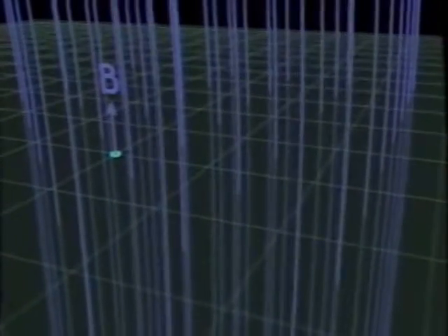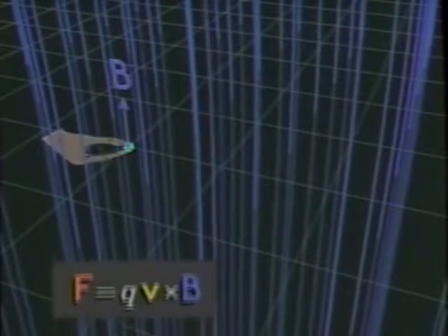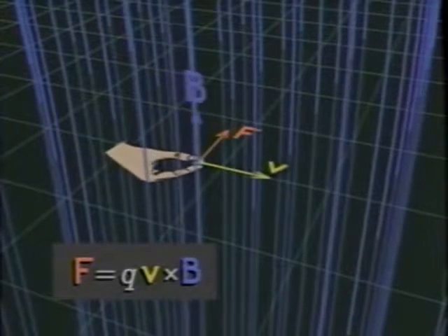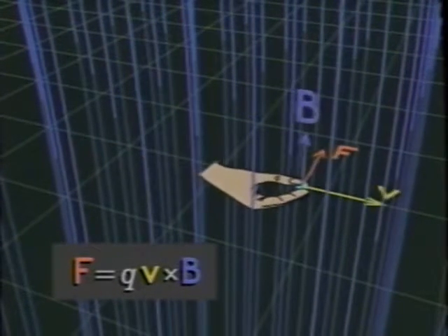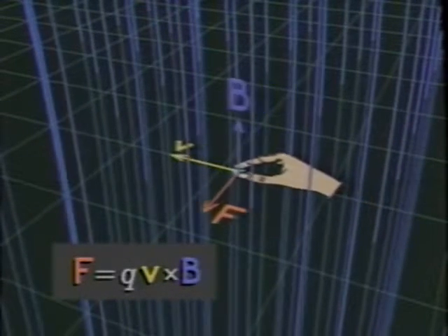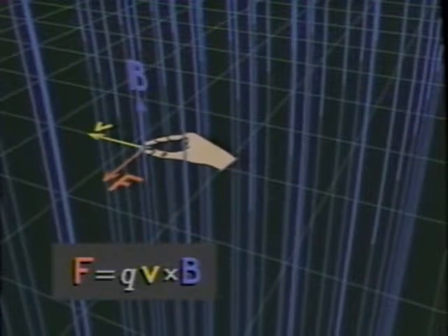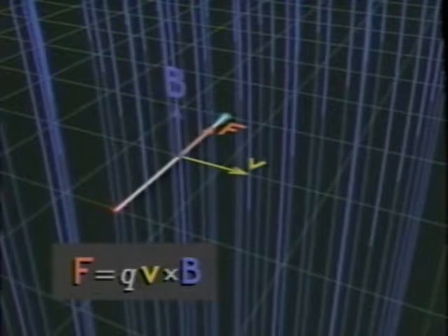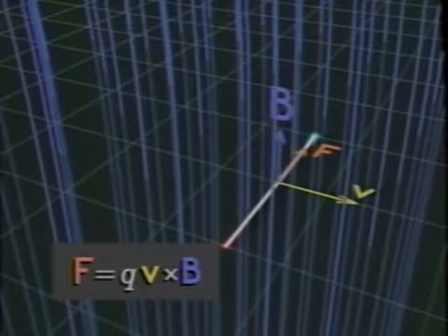How does electromagnetic induction really work? In other words, how can a magnetic field drive an electric current around a circuit? Magnetic fields apply forces to electric charges, but only if the charges are in motion. The direction of the force is perpendicular to the velocity and the field, and depends on the sign of the charge, in this case, negative. For example, the charges might be electrons in a piece of wire.